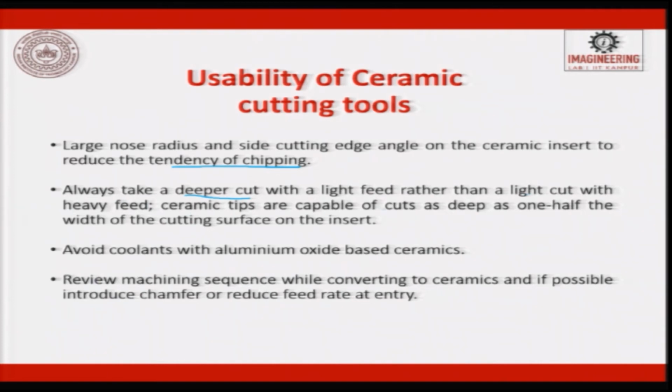Ceramic tips are capable of cuts as deep as 1/2 the width of the cutting surface on the insert. Avoid coolant with alumina based ceramic tools, because when coolant is applied at high temperature, there will be a thermal shock, and it will shatter or chip off. Review the machining sequence while converting to ceramic, and if possible introduce a chamfer or reduced feed rates at the entry. So, as soon as it enters, no impact load, slowly it enters and then it increases the speed.